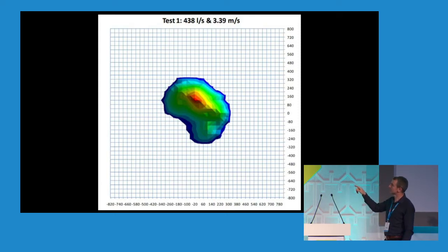But the most remarkable thing is the total flow, which is the other figure, and that's 438 liters. So if you try and imagine what that looks like, it's a big volume of air coming out of that machine every second. And there's only 25 or 30 liters a second being drawn in. So there's a huge amount of amplification going on there just because of that effect, which I demonstrated with the ball.